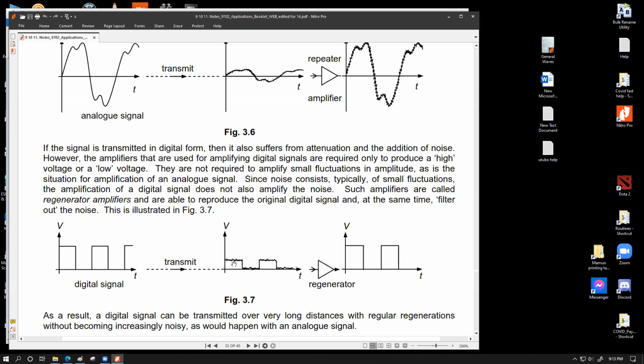So if this value is, let's say, more than 1, it applies its own full voltage over here for the same duration. And whenever it is close to 0, then it applies perfectly 0. So this is sort of like a comparator circuit. Let's assume that, given the transmission path and the amount of noise we can pick up, this 0 signal can have a maximum value of, let's say, 0.1. So it cannot be more than 0.1.